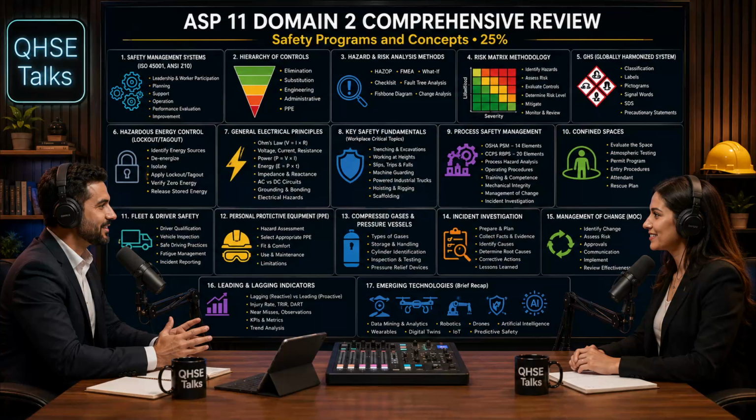The problem says it's a 40-ton counterweight. But here is where people make a fatal math error on the exam. They mix their units. They absolutely do. We used pounds for the load, so we have to use pounds for the counterweight. 40 tons multiplied by 2,000 pounds per ton equals 80,000 pounds of force.